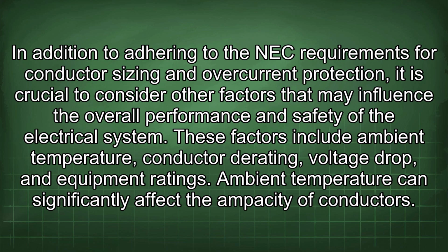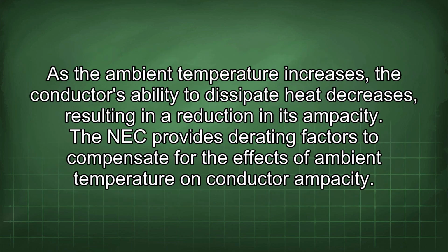In addition to adhering to the NEC requirements for conductor sizing and overcurrent protection, it is crucial to consider other factors that may influence the overall performance and safety of the electrical system. These factors include ambient temperature, conductor rating, voltage drop, and equipment ratings. Ambient temperature can significantly affect the ampacity of conductors. As the ambient temperature increases, the conductor's ability to dissipate heat decreases, resulting in a reduction in its ampacity.